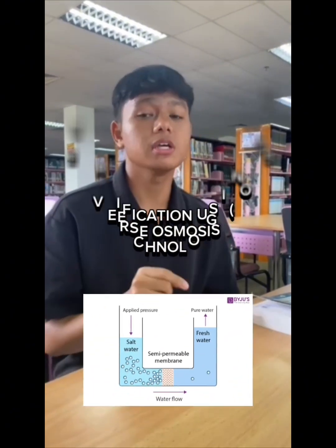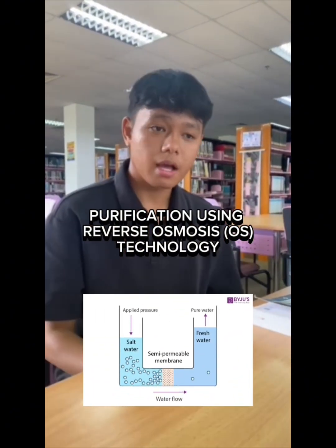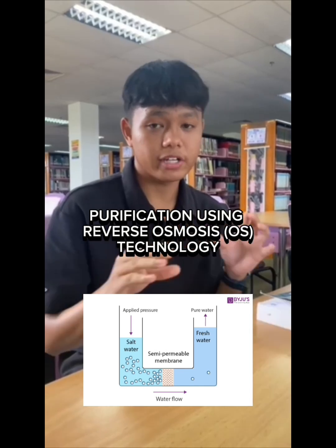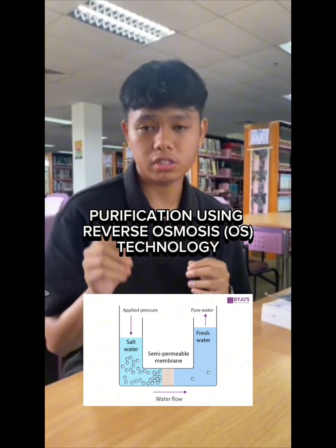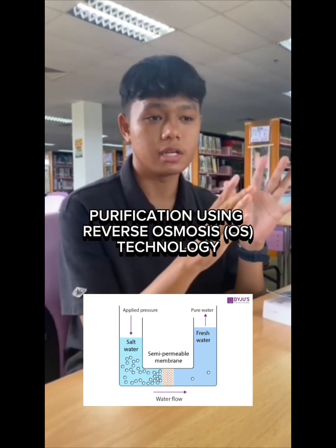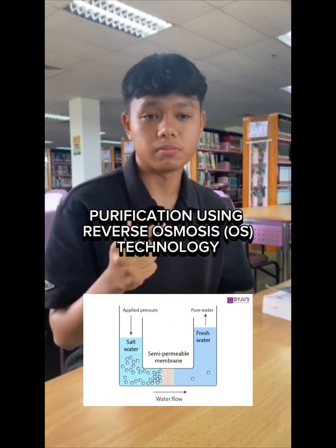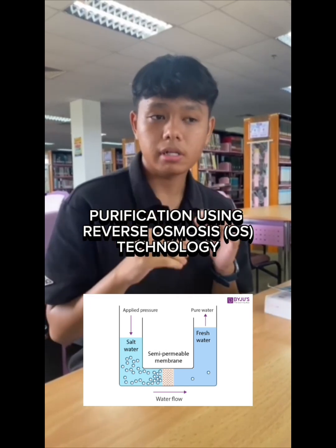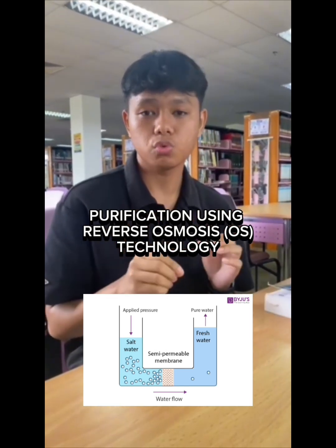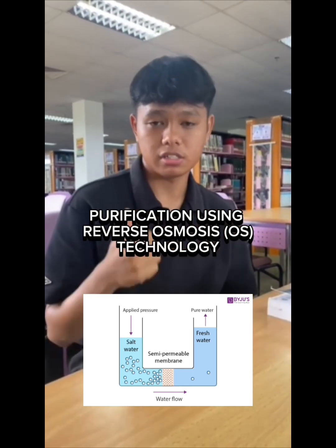One civil engineering solution to reduce the impact of high calcium level in water is purification using reverse osmosis technology. Reverse osmosis is a water purification process that involves forcing water through a membrane that lets small particles pass but blocks others, like bigger particles, to remove dissolved salt, minerals, including calcium and other substances. The membrane allows only water molecules to pass through while blocking larger ions such as calcium, magnesium and other hardness-causing minerals. There are several benefits of this reverse osmosis technology.